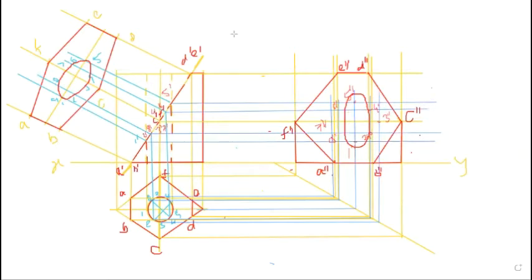So when you draw the hatching line, here only this part is not the section part. So the hatching line starts from this. And in the circle, in the whole circle section, there will be no material removed. So in the circle section there will be no hatching. Okay.